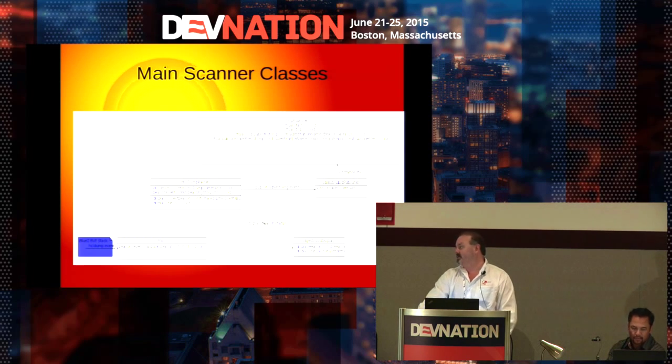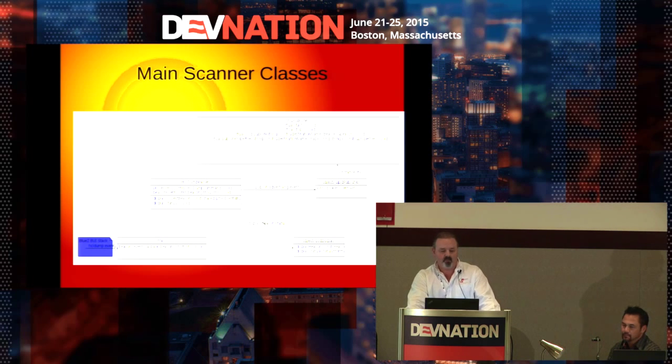We also had a mechanism: the scanner we had up on stage in the keynote was connected to an LCD display, which was another way we debugged the status of the scanner itself, and tested how well it could filter out different beacons. As we did in the demo last night, if you move into the scanner, it would lock onto different beacons based on their RSSI signal strength and display information about that beacon, as well as the status of the scanner itself. Early on in development there were circumstances where we had memory leaks or other issues, so it was helpful to have the memory usage and CPU usage displayed on the scanner itself via an LCD display.